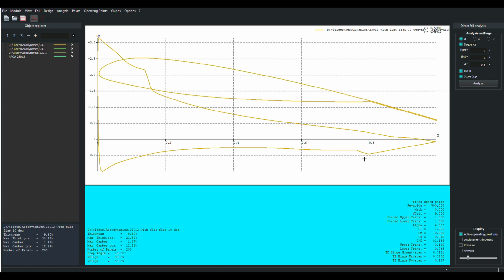There, they're off. And what we see is the flap is now kind of aligned with the aft surface of the airfoil. So even though at this point we've deflected the flap down 10 degrees and we're getting a nose down pitching moment, we're not asking the air to turn a corner here. We've gone from a concave to a flat scenario.